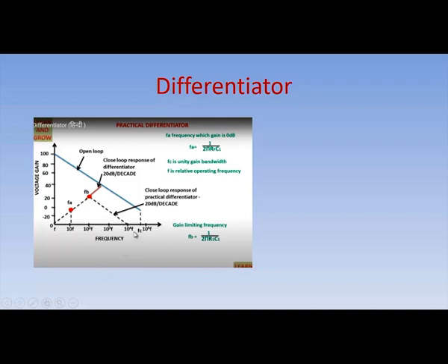If the frequency is very high, the circuit will get a stability problem. The gain increases beyond the limit and it goes to instability, so it breaks into oscillation after one point of frequency.